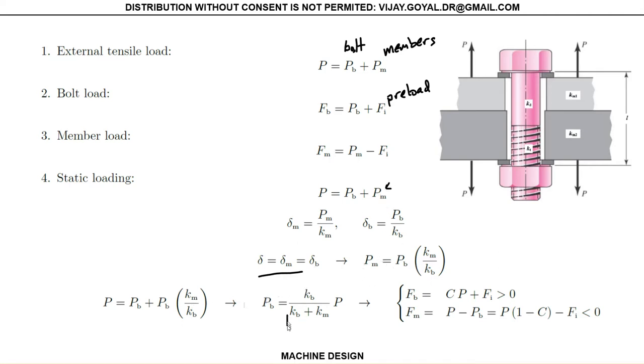And if you remember from a previous class, this was your joint stiffness constant. That's a C. So in other words, you can rearrange this as follows. Everything can come in the following form. This has to be less than zero. Remember what I told you? It has to be less than zero, because you want to make sure this is in full contact, and the tension bolt is doing its job.